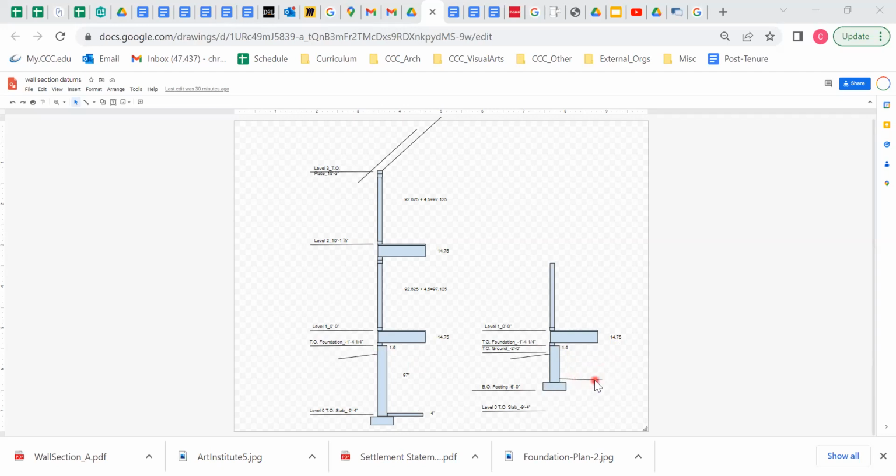Sometimes it's just sand and perhaps some rock that allows for good drainage under there. Generally speaking, you wouldn't heat or cool this crawl space. You would put insulation in the floor. And one important thing you would need to do is make sure that it vents so that you don't get moisture trapped under there. But this is basically what we're going to be doing for the second structure.